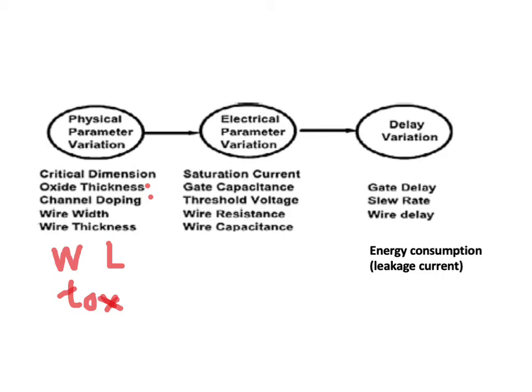So the number of dopant atoms required to have a heavily doped N well or P well, you can actually count on your fingers. So even a small deviation, like say you reduce one dopant atom, would cause a large change in the percent dopant profile of the transistor.